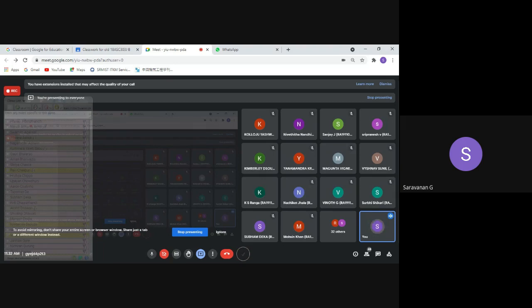Stagnation corresponds to the chamber: Pc, P naught. For the other area, it is any location, maybe throat or maybe exit, it is P only. So P is P, T is T. It may be Pe, or T may be what I call Ta. Similarly, it may be Te, or Tt, or Tc, whatever it may be. So like that, the stagnation only corresponds to the chamber. From the reservoir, that will always be stagnation. So we are relating stagnation and static to get the Mach number relation as well as velocity relations.